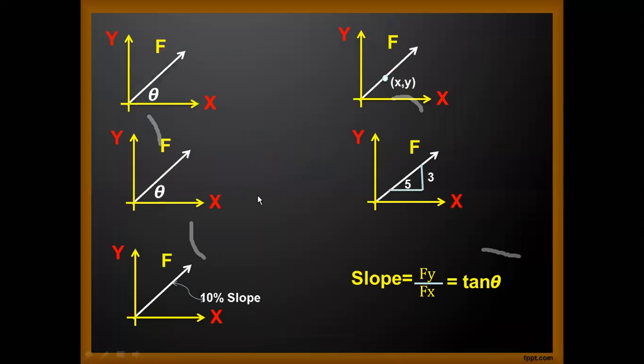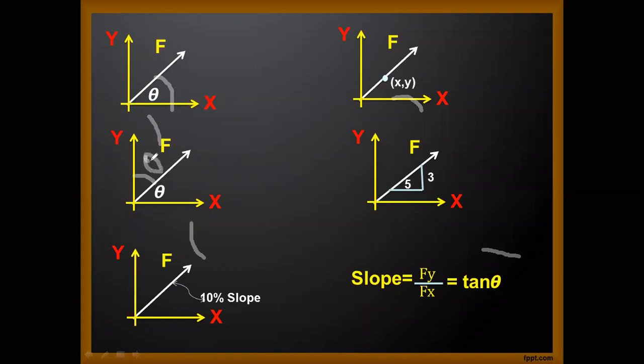Okay. Next one, here you see some of the conditions I have given to solve the resultant of an inclined force. For example, if they directly give the direction of the force, that is f, then this will be f cos theta and this will be f sin theta. The same way, sorry, here I have mentioned with respect to horizontal. If theta has been formed with respect to vertical, then the horizontal component is f sin theta and the vertical component is f cos theta.